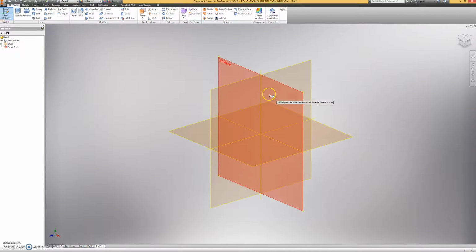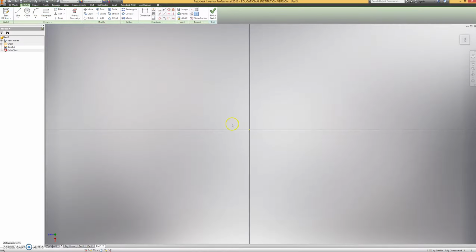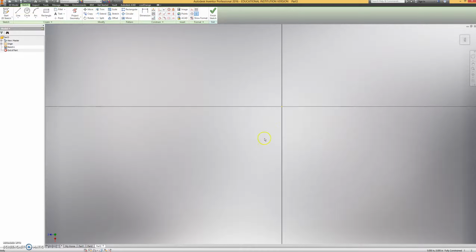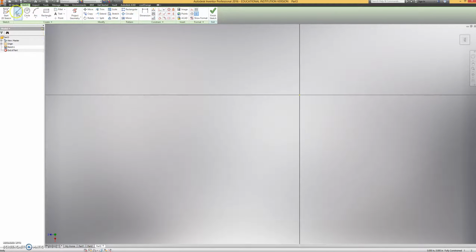Create another 2D sketch, select this plane, and I'm going to build this in the lower left-hand quadrant using the line tool. So I'm going to start on the origin, drag off to the left. This would be 2 cubes long, so 1.5. Drop it down, 0.75. Bring it in, 0.75. Another 0.75 going down, and one more off to the right. My final line, I need to bring it back up and connect to the origin point here.